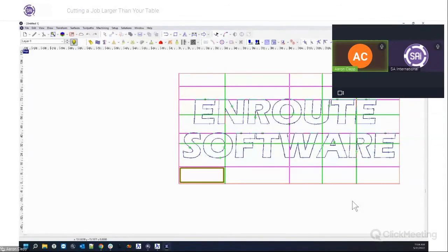Even with this kind of stuff here, this is a fairly easy thing to do. Even if the design were a little more complicated than this, I would say that toolpathing and vector cutting is really easy in terms of scaling it to larger sizes. The tricky thing will be if you wanted to create a 3D panel that was, say, twice the size of this. You might run into some problems with that, just because 3D takes up a lot of memory and a lot of processing power.